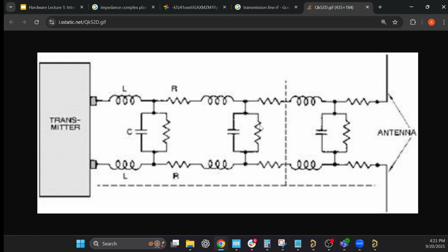From a simple perspective, a coax connector or a wire just instantly links point A to point B, and there's nothing magic happening in between. But at high frequencies, that model breaks down, and really what's going on is that at each incremental aspect of the line, every infinitesimally small part of it, it is slightly a resistor because it's not perfect. It's slightly a capacitor because you have some distance between your ground and your power, and it is slightly an inductor because you have parallel current flow.